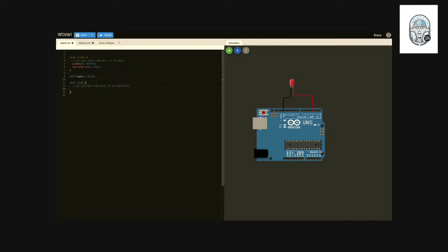In here we can simply move our digital write. There are two routines: the setup routine and the loop routine. The setup routine is called on startup, and it's only called once unless your board crashes, in which case it's called again. And then there's the loop, which is called multiple times. You're actually supposed to leave the loop routine, and it's going to get called again.